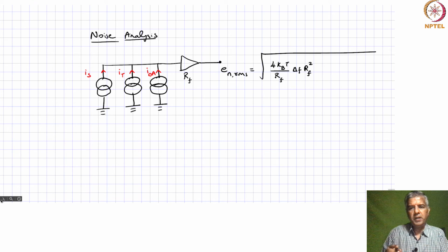The variances of these individual processes add. Now we are considering three different processes which are independent of each other, so the variances corresponding to each of these processes add, and then you take a whole root of that, and that's when you get the RMS of the combined noise. So that's what we are doing.